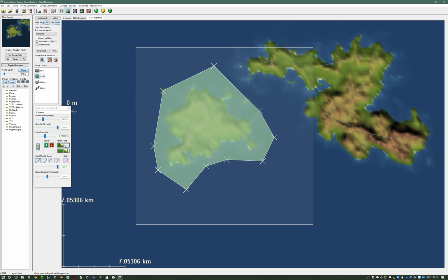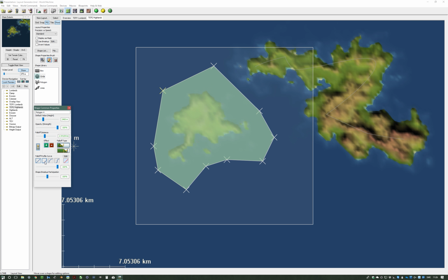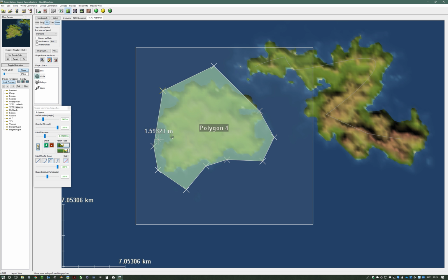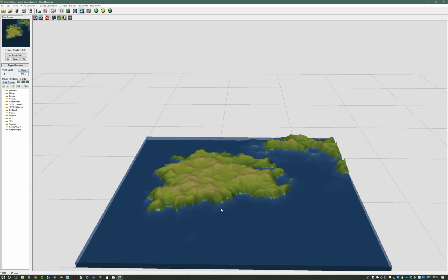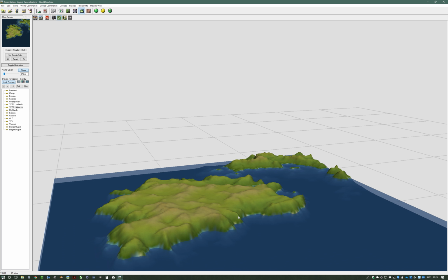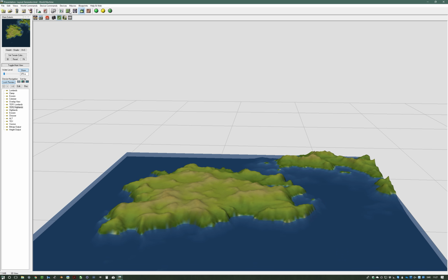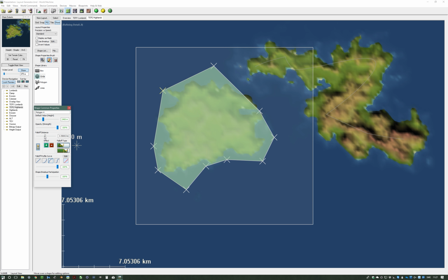And in order to make this work, you need the next interesting thing, and that's the fall off profile curve. You can make the fall off different. You have a standard curve, meaning it just goes from 100% and then gradually smooths out. But you can also create the opposite. You can have a curve that looks like this, or you can have a curve that looks like this. And now if I use this curve and have the fall off on the inside, all of a sudden it can start looking really cool this way. And here I have something that's starting to be useful. I should probably increase the fall off just a little bit.